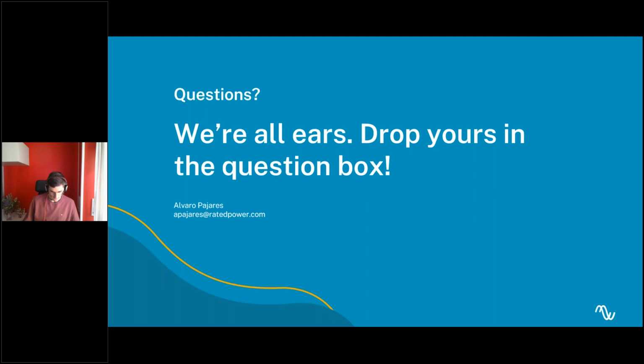So we have another question, which is: normally the calculation of the number of modules per string is done with data that has hourly resolution. Have you checked if having sub-hourly data affects the calculation of the number of modules in series? Thank you very much. So here there could be differences, but we didn't notice any, and normally it's because